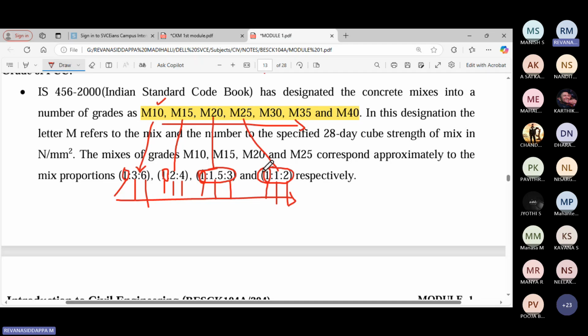Up to a certain limit, as you increase the quantity of cement, the strength of the concrete increases. After the quantity reaches some threshold value, the strength decreases. You cannot use it in the reverse way. You cannot use three portions of cement, one portion of sand, and 0.5 portion of coarse aggregate.